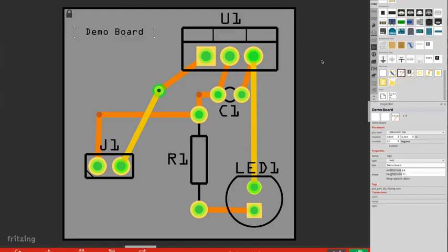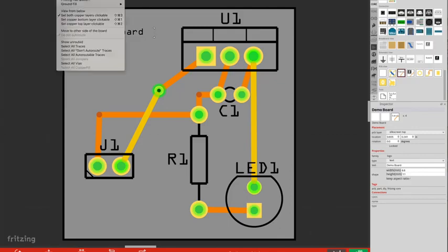We're closing in at the end of this presentation, just really the last and perhaps one of the really important things to do. So we've designed our board. How do we get it into production? Well, the first step of that is to check that it is actually producible. At the top, in the routing menu, you will see something called Design Rules Check.